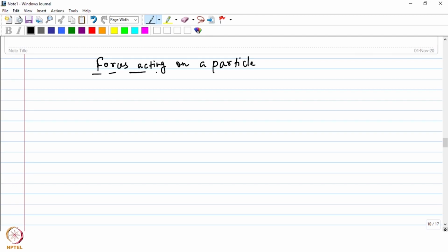This also needs to be considered when you talk about particle distribution, because this will also have an influence on how the particles will be distributed, or whether they will be pushed by the interface or engulfed by it. So engulfing or pushing will also depend on the forces acting on the particles.